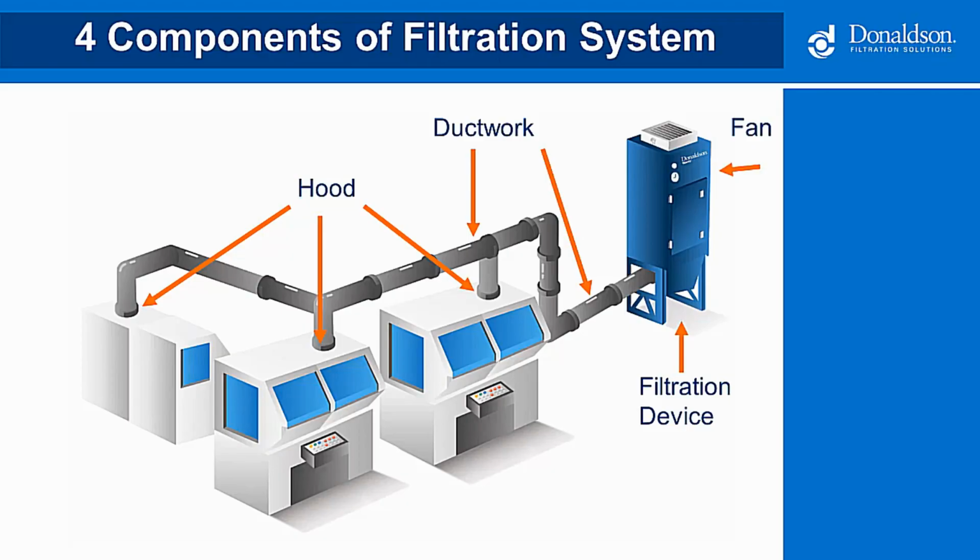If you incorrectly design any of these components, your system may not perform to expectations. So it's important to understand what goes into designing an industrial ventilation system. Now, I use that word industrial ventilation because this is totally different from an HVAC system. HVAC systems move clean air, and we are moving material, which is a whole different animal.